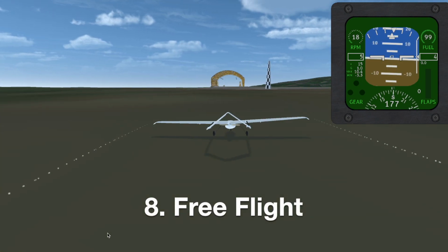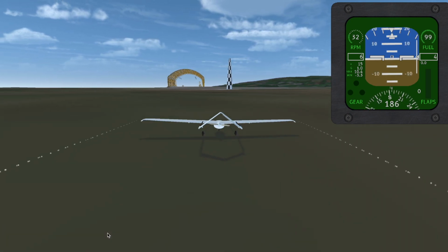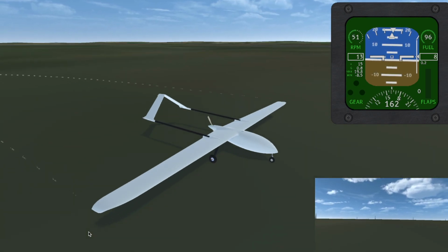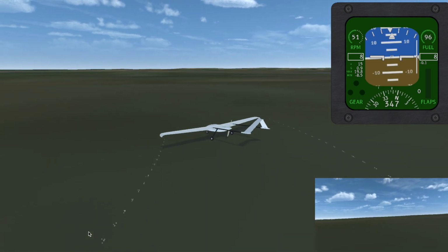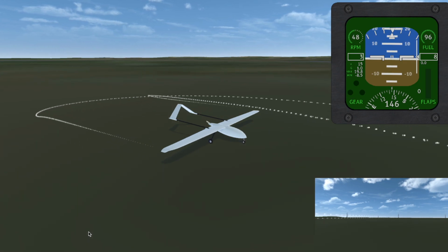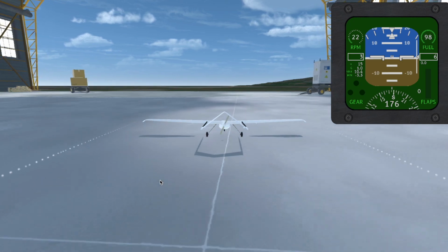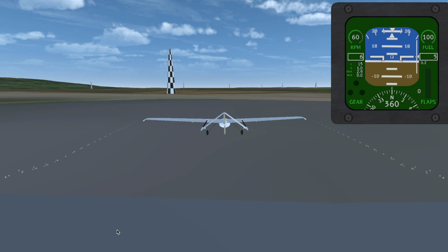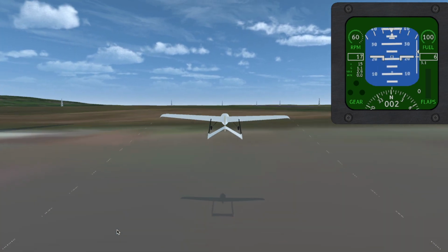The aircraft responds well to rudder inputs when maneuvering on the ground. As speed increases towards 10 meters per second, the rudder control results in a greater angular acceleration of the aircraft, which sometimes results in the wingtips dropping towards the ground, and the aircraft velocity vector is no longer aligned with the wheels, which results in the aircraft drifting. As a result, it is recommended that the aircraft maintains a slower speed at maximum of 6 meters per second when taxiing.